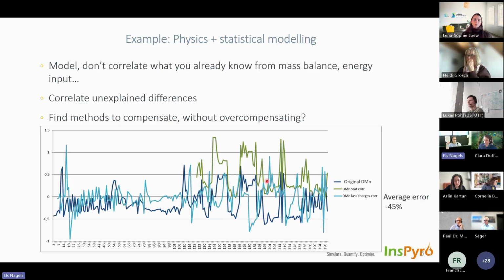You have some deviations. But by looking at the differences between the expectation and the measurement, so you bring together the model and the numbers, we could even detect which suppliers were off spec. Normally you cannot do that, because you have a feed mix, you have multiple material suppliers, they go in one pile and are molten all together. But by analyzing the differences between expectations and reality, we could decide, okay, this supplier delivered off-spec material on that day and so on. So that was actually a very interesting project.